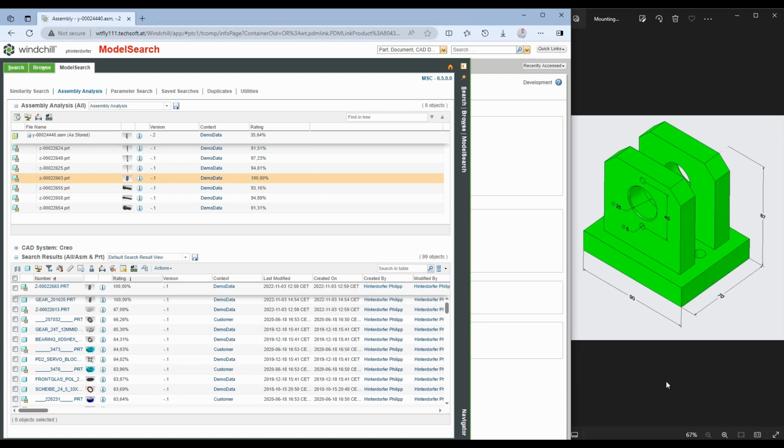But there are other ways to figure out if this model already exists in my database. Because if you need models, then you always know at least some geometric information. In that case, I'm quite sure you know at least approximately the length of the model, the width of the model, the height of the model. And then you may also have additional information like the hole diameter of 25, or there are two holes with a diameter of 5 and the hole bottom distance of 40.